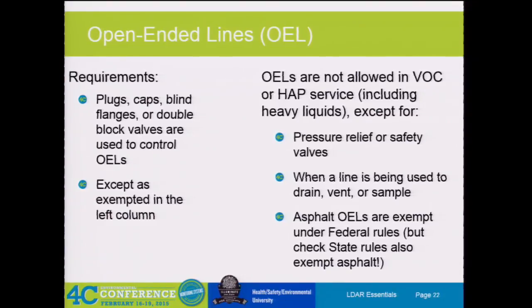So OELs are not allowed in VOC or HAP service, including heavy liquid. What is the only exemption if you read the rules? How many folks have actually read their LDAR rules? Okay. So the only one is basically asphalt. Asphalt allows you to have it because it causes a big issue. There's a few other ones in there on the OELs when you read that you can have a few exemptions. And if it's going to cause immediate danger, they allow you to have it where it's basically a vent.